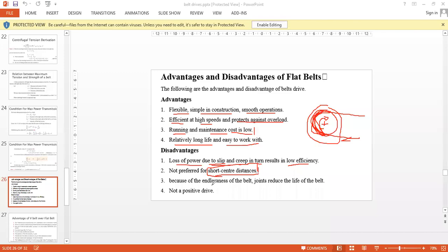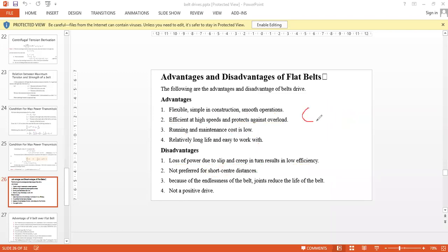The next thing is that for an open belt drive or a cross belt drive, whenever we go to a flour mill, we may see that over this pulley, if we have this belt, there will be joints made like this wherever the belt is being cut. The more the number of joints on this belt, the more power loss, because at this particular portion the belt is not flat, so there is no contact over the pulley, so there will be a slip over here.